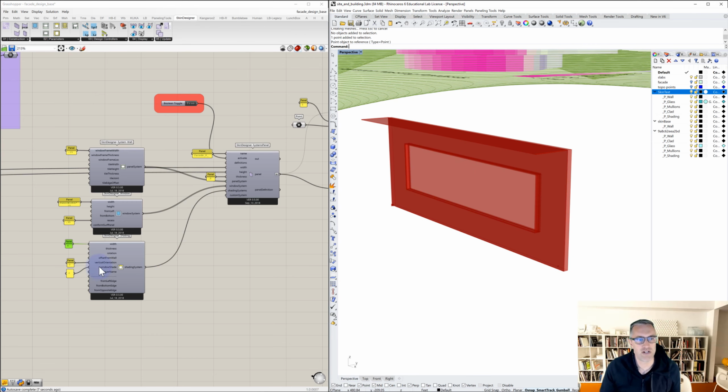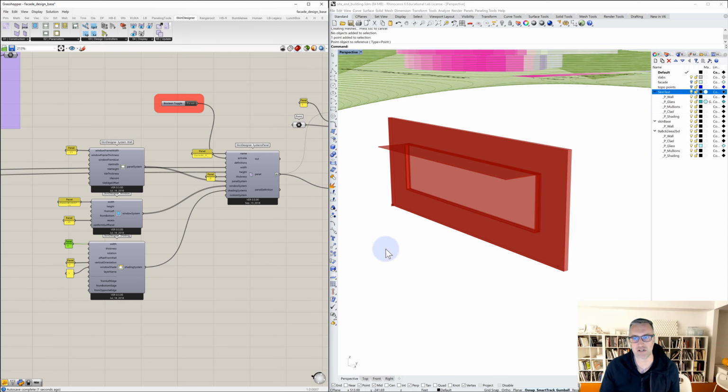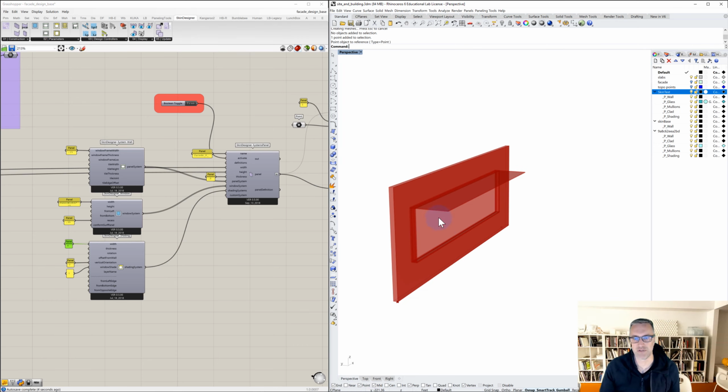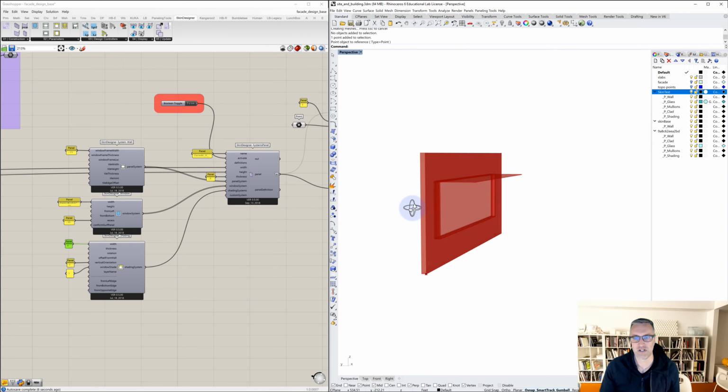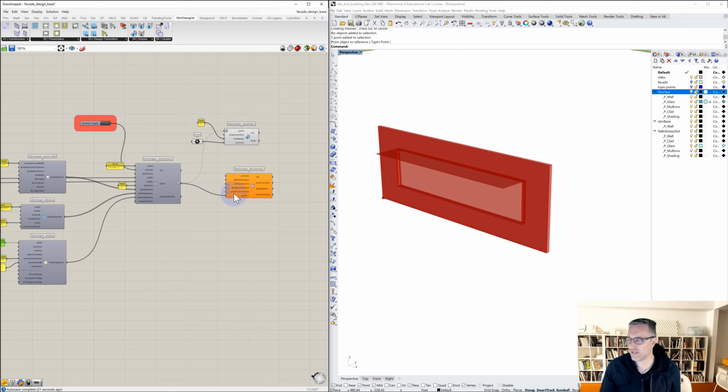And if we set window shade to be true, in other words, change that to 1, this is going to make it just at the height and at the width of the window. So that's a really smart, really simple true/false or boolean condition, but it gives us some intelligence within the shading element. So that's nice as well. So we can leave these as they are. All of these things seem to be working, and that's good. Let's take a look at what else we need to do.